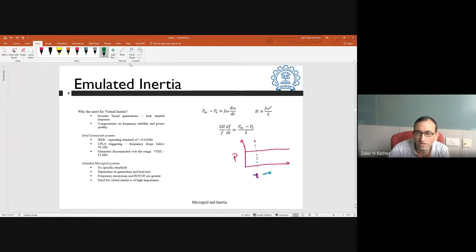It can increase the power output. So it's going to be somewhat like this. It is going to increase instantly, or you can say quickly, it's going to increase the power output. If you employ an external controller, what we call an inertial controller, that passes on the frequency information from the grid side to the controller side, and it forces the energy system or energy source, be it wind, solar, battery, to increase the power output. That is how it works.